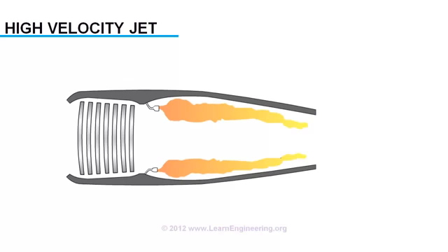Air gets into the engine by the forward motion of the engine and the sucking effect of the compressor. The diffuser increases the pressure of this fluid to some extent by converting some part of the kinetic energy to pressure energy. After that the compressor comes, where both pressure and temperature of the air are raised by energy addition from the compressor. So at the outlet of the compressor, we will have air at high pressure and high temperature.